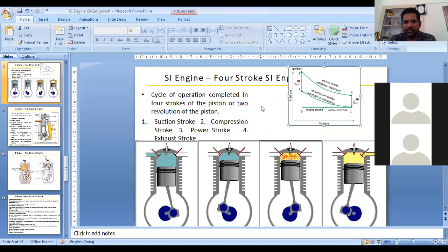At the end of the compression stroke, the fuel which is going to be drawn into the cylinder is in the form of fuel jets, using the fuel injector. It is just like, at very high speed, the fuel is sent to the cylinder in the form of jets, or small droplets. Due to this, each fuel droplet is surrounded by very high temperature compressed air particles.